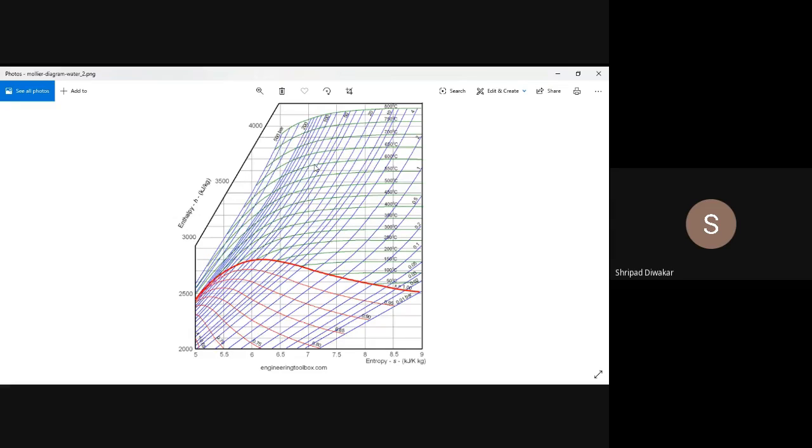In this zone, we are going to concentrate mainly on pressure and temperature. In the other zone, we concentrate mainly on the pressure lines and dryness fraction lines, because the temperature is below 100 degrees Celsius and the steam is in wet condition. Whatever the temperature, the region above the saturation line is above 100 degrees Celsius.